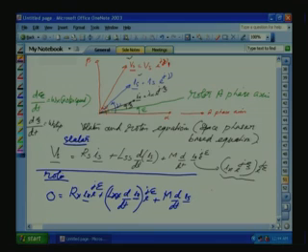So, IS we have to bring back to the rotor circuit. IS is originally defined with respect to alpha, now we have to define it with respect to the rotor. So, we have to go this way. Previously for the rotor it was plus j epsilon. Here we are going this way, the angle is reducing. So IS into e raised to minus j epsilon. This is the voltage term appearing at the rotor due to the stator current. Now this voltage term also we have to bring to the stator side. So outside we have to multiply it by e raised to j epsilon.